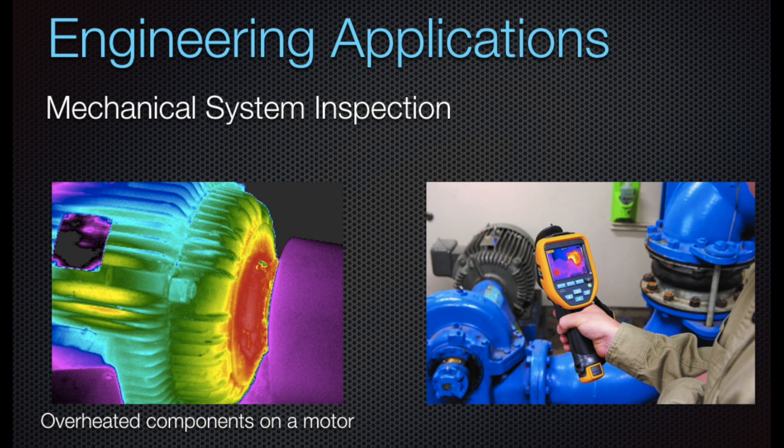thermal image. Although they are not clearly exposed, the bearings of the motor are often a source of overheating due to poor lubrication, general wear, or even the fact that it is simply a poor bearing choice. Regardless of the specific cause of the bearing malfunction, infrared thermography can be used to detect a potential source of failure of this motor and indicate that further maintenance is required in order to prevent severe consequences.